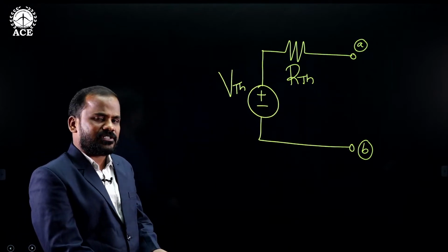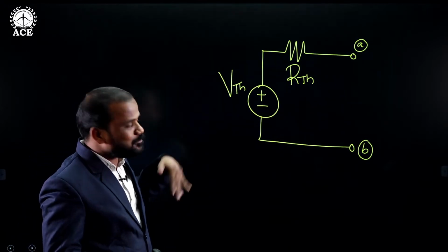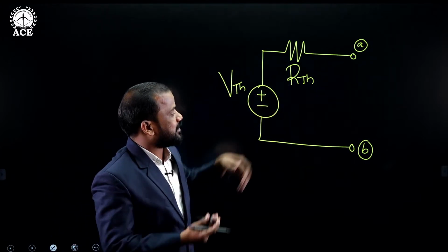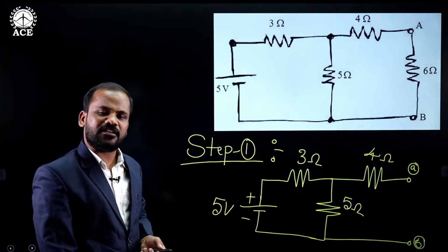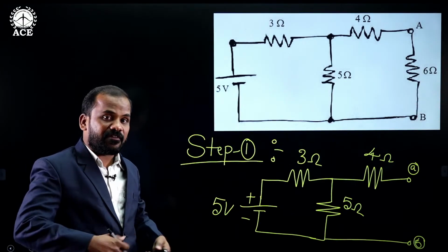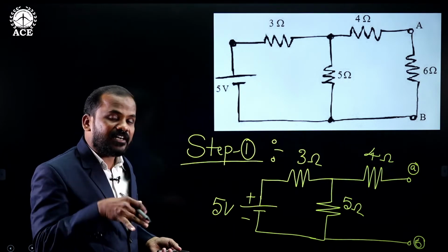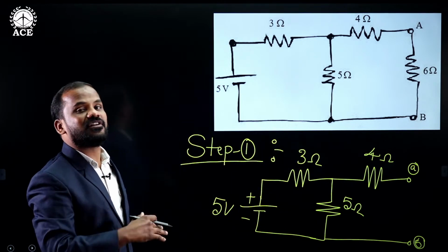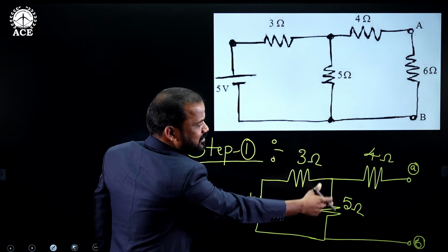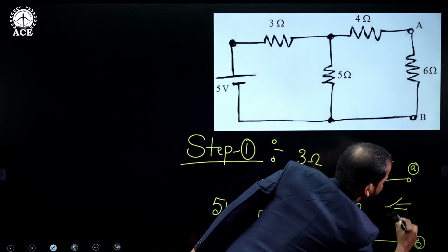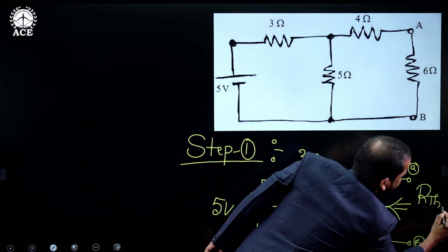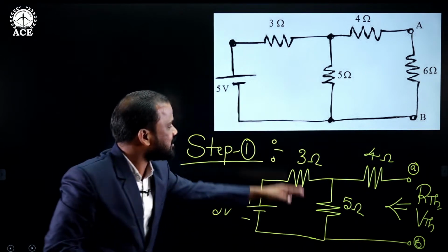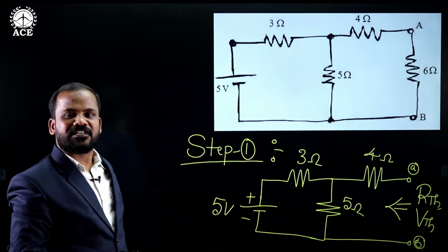But how is it possible? Simple. It is possible by finding the value of Thevenin's voltage and Thevenin resistance from this particular two-terminal linear network. We need to find these two values across the terminals where we disconnected the load resistance, that is, across the open terminals here.